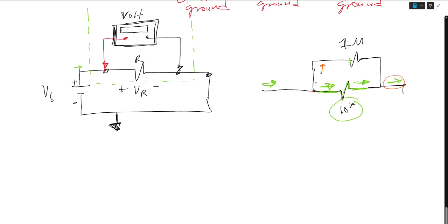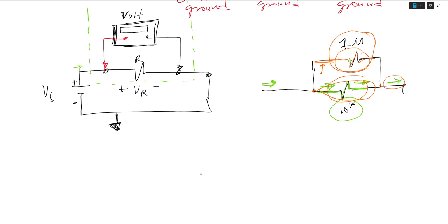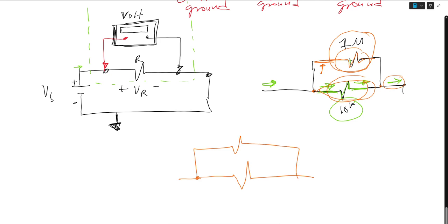And what we do now is we measure that voltage through this parallel configuration, because since this is in parallel, the voltage that drops through here is the same voltage that would drop through the 1 mega ohm. And again, the way to prove that based on voltage difference is we defined the voltage difference to be 2 points, where the 10 kilo ohm and the 1 mega ohm resistor share a VA and a VB.